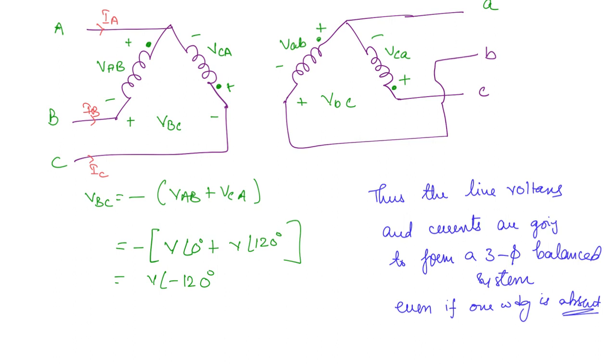One thing that you have to note here is that these all form a 3-phase system, which is well and good, but the magnitude that is going to be present is going to be different from the original magnitude. So the power is going to differ. Now the total power cannot be delivered, only some part of the power can be delivered. So what is that amount of power? Power delivered in open delta connection.